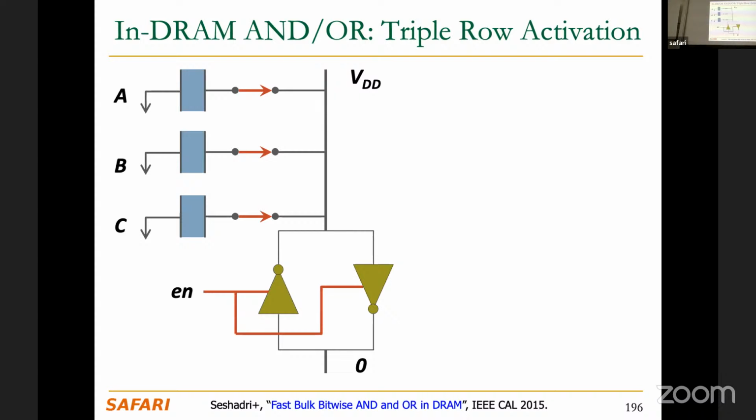So I was wondering if instead of this, we could do something like, instead of having this 1 bit line, we would have 2 or 3. Inside the DRAM subarray, we have around 65,000 of those already there, together with the circuit here. They don't share the circuit. Each one of them is an individual one. So you can do 65,000 of this majority at once.